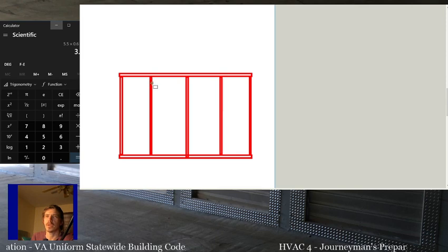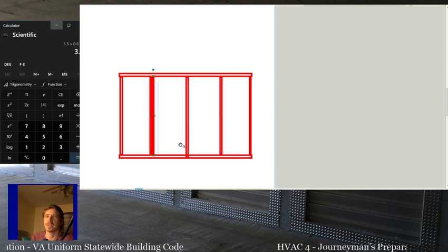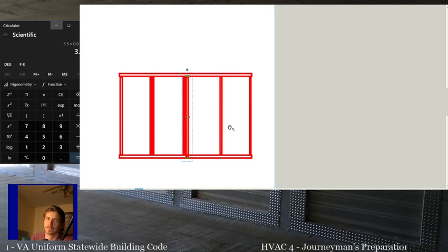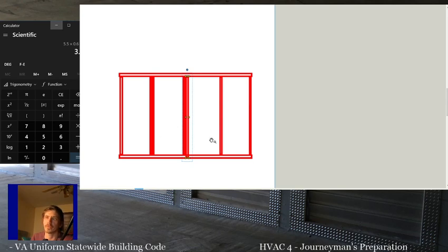So if we put another stud next to this stud, and we put another stud next to this stud, right? We double up the stud, then we can drill the bigger hole, but we can only do it through 2 studs. So if we need to go through a third stud at 2.5 inches on a 2x6, we can't do it, because we can only go through the 2.